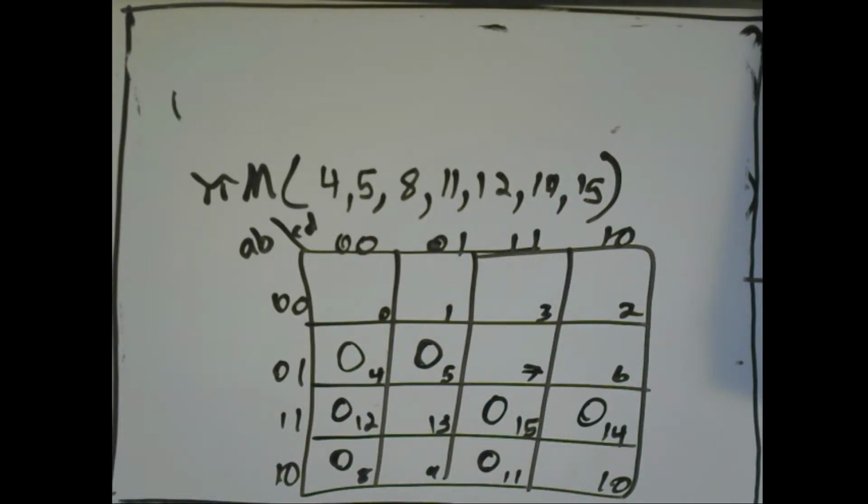So I have my maxterms sorted out, and I'm going to do the exact same thing I did for the minterms. I want to create the biggest prime implicants. So I'm going to evaluate what I can circle. I'm trying to maybe get a group of 4, but I don't think there's any way of getting a group of 4 with this one. So I'm just going to circle what I can.